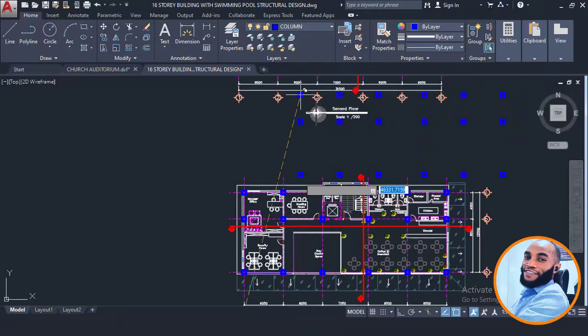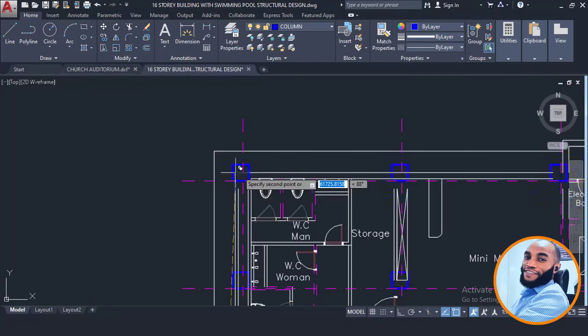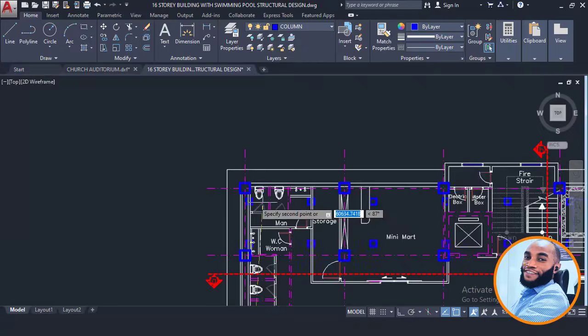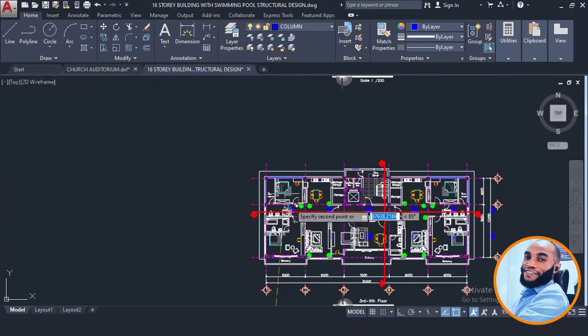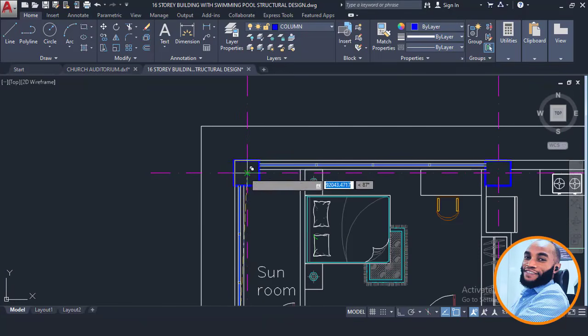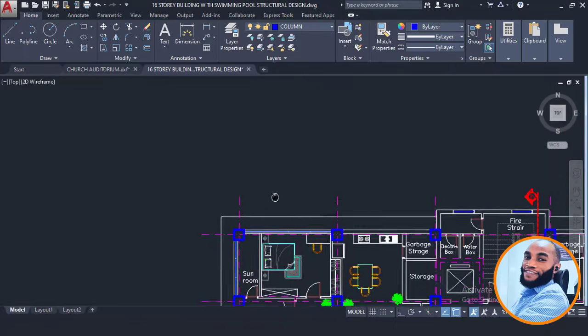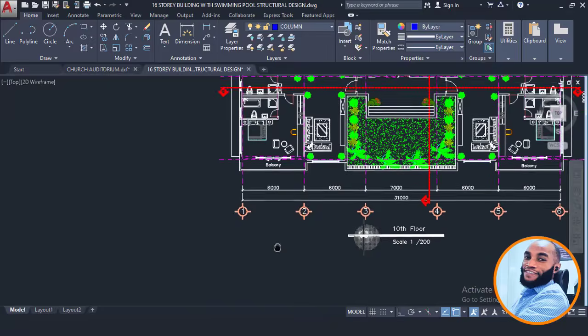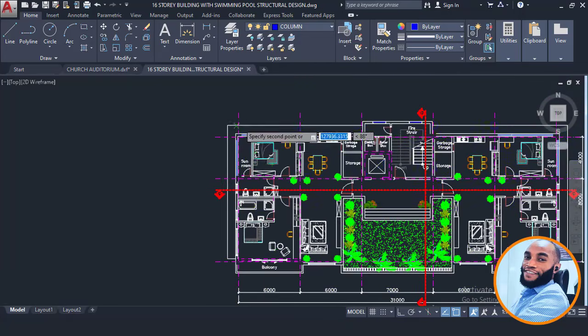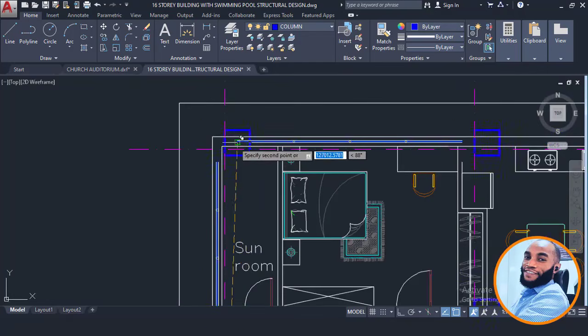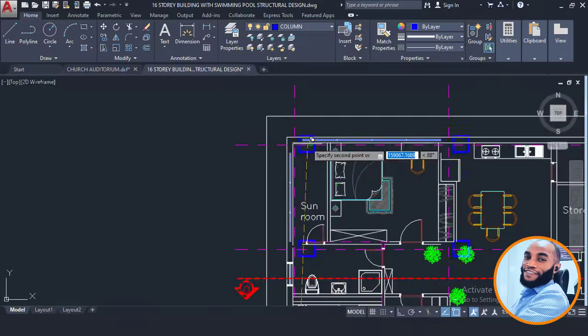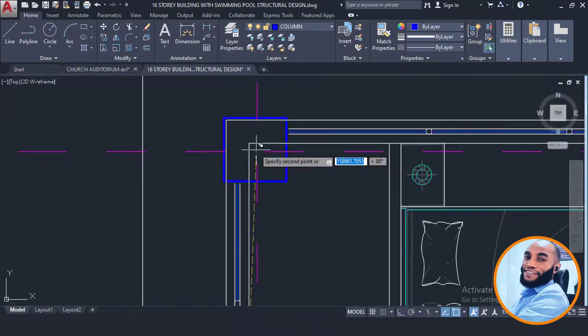Okay, and I'll paste again here on the other floor. So make sure you paste it on all other floors to make sure that everything is looking the same, and then check if the column points which you have put on the ground floor are causing obstruction on all other floors. Okay, so I'll do just that right now by placing all the columns there just now.